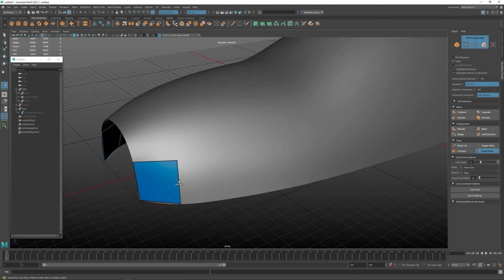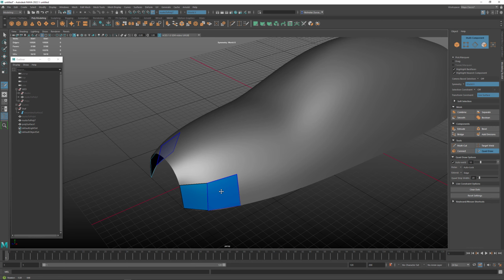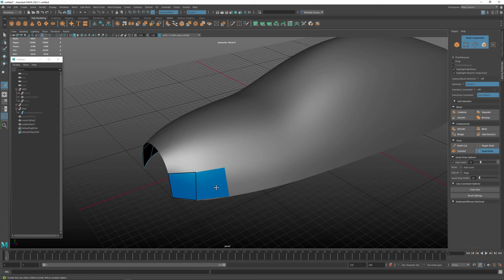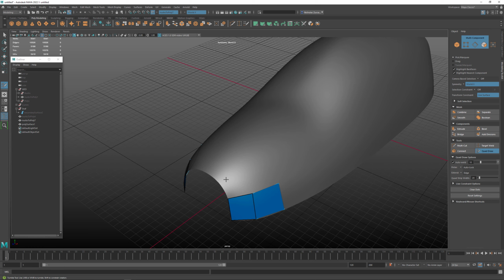Okay. If we hold down Tab, we can drag out. And if we have the polygons with these verts that you see here, you can just click on the verts and you can move them around. Think of this as like 3D tracing. It's kind of cool that we have the surface, and from having the surface, we can just drag out these points and hold down Shift like that. And I'm going to lay down another point and another point here, hold down Shift. And if we drag them really close together, we should get these points to just snap together pretty easily.